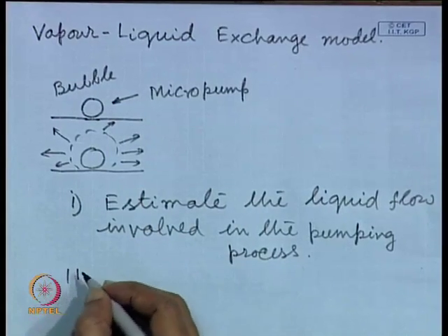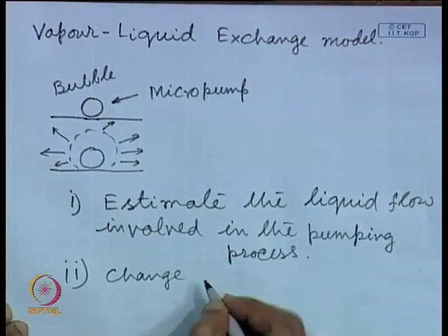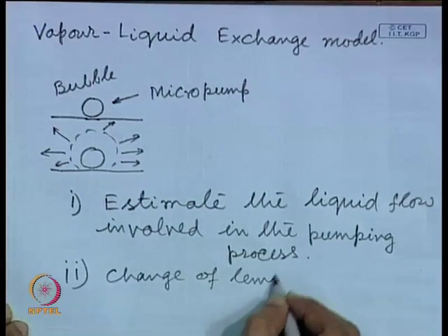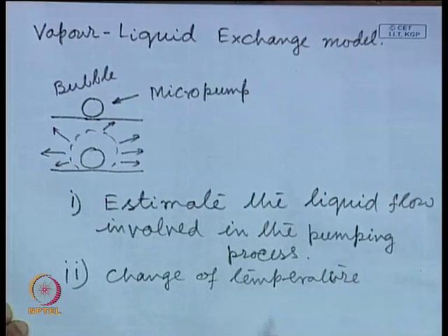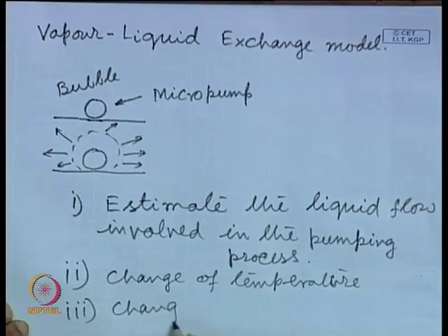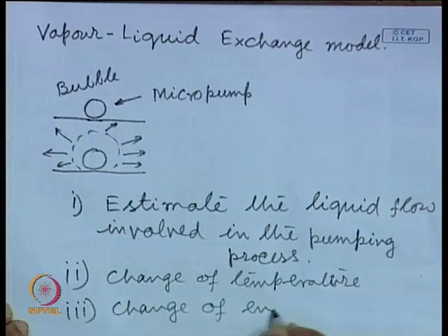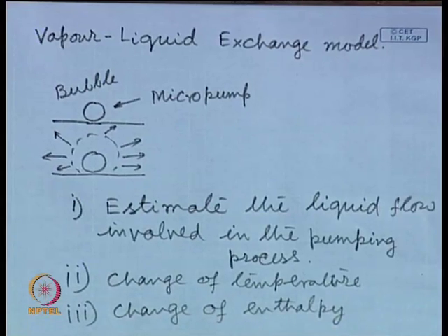And then one has to find out the change of temperature of the fluid, and then from there the change of enthalpy. This change of enthalpy is nothing but the heat being taken from the wall. So, this is how your heat transfer due to this pumping process can be estimated.